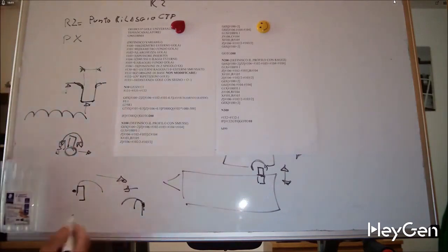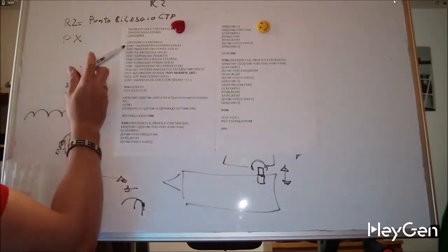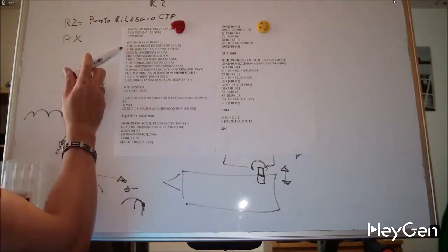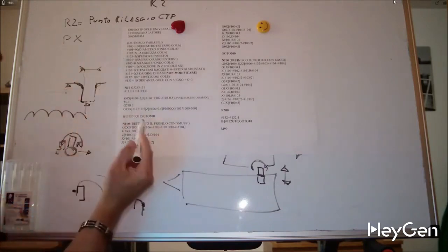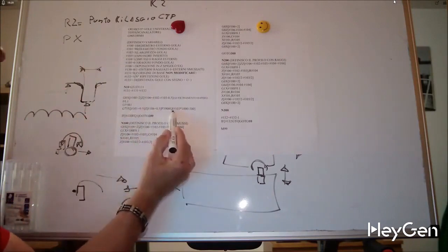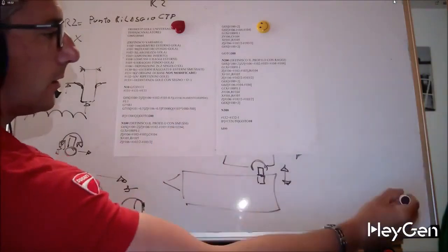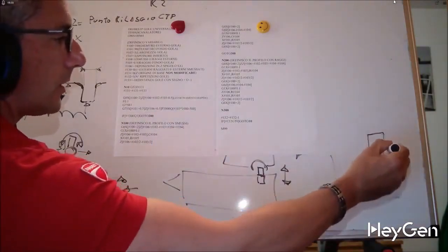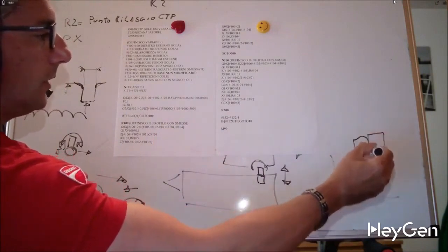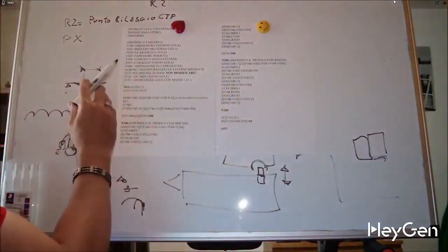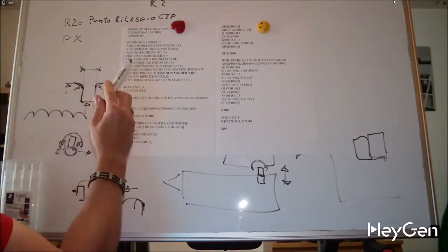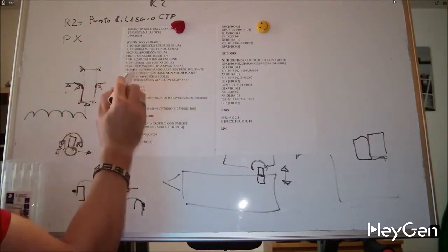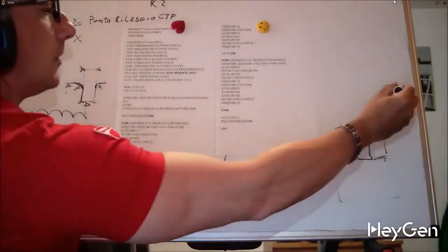Let's comment together. I've determined the outer diameter of the groove, the bottom groove diameter, the width of the groove, and the thickness of the insert, because obviously with the G75 macro that we studied earlier, we need to specify how much an insert should move, say 3 millimeters in a 6-millimeter groove, to widen it completely. So I need the thickness of the insert, the size of the chamfers or radii, the bottom groove radius. You see, these are all variables.